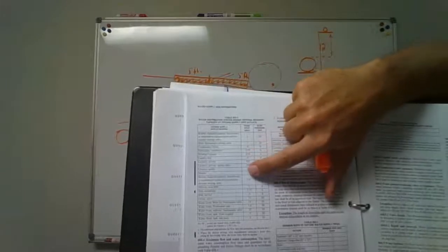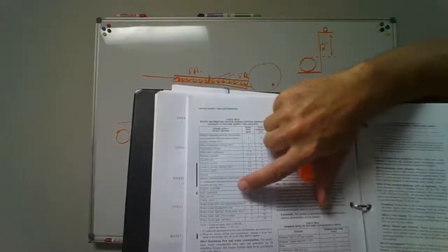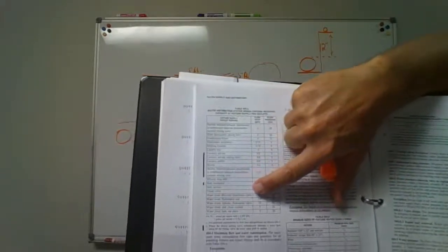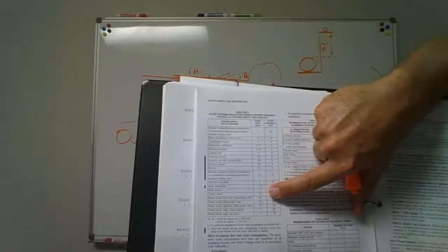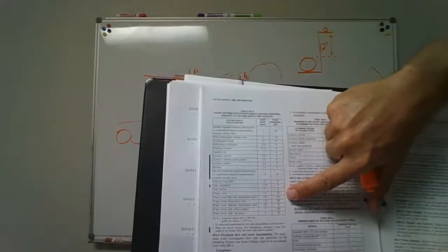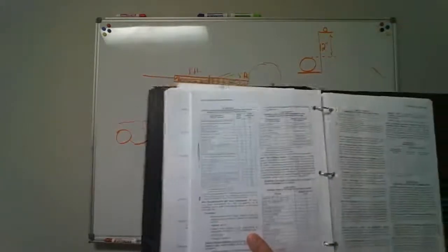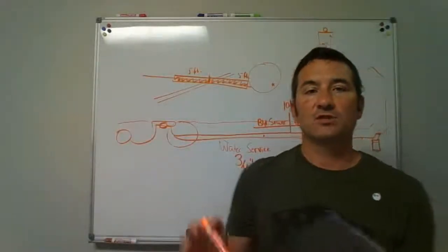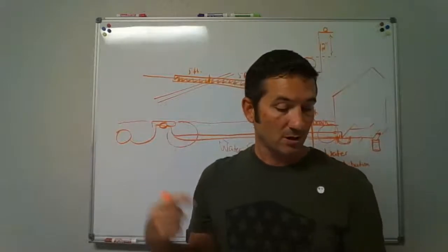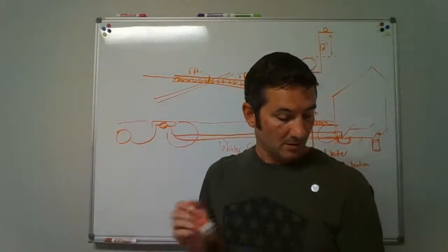Now you will notice as you get higher, as you get down to here, like water closets, flush meter valves, you're going to have a higher number of gallons per minute and higher pressure ratings. When we talk about how those work, you've got to have a certain amount of pressure just to get that flush meter valve to shut off and quit continually running.